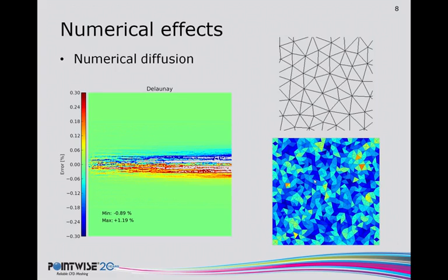So there are a lot of cells that have very low skew, but then there is a tail of cells, a probabilistic tail, that has significant, if not even high, skewness in these triangular cells. What that does is it introduces a cumulative error. So as the profile is advected further and further downstream, these errors compound one another, and the overall error in the solution grows larger and larger.